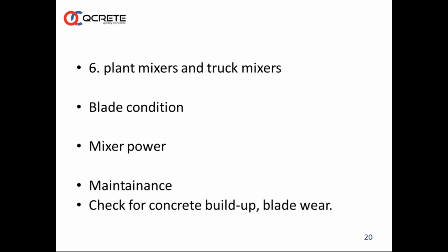Plant mixers and truck mixers have to be in good condition. They have to be maintained and repaired as per schedule. Blade condition is important. Mixer power too. If there is a lot of accumulation of old debris, old concrete set on the walls of the drum, and it is not removed, chipped off or cleaned in time, the mixer power will increase, and it is a waste of money and resource. It may also lead to some quality problems.